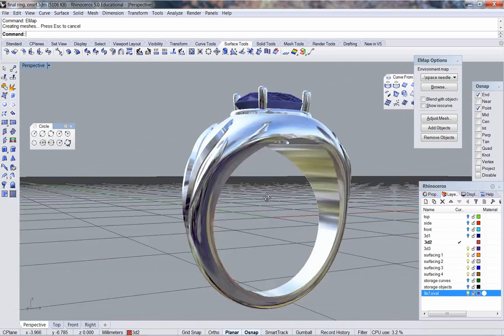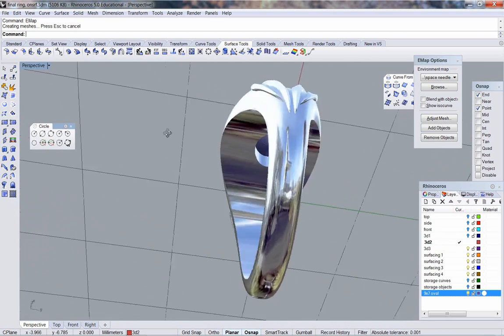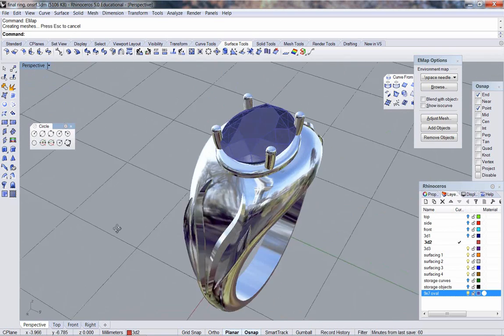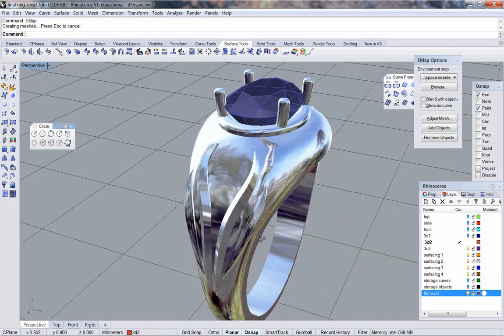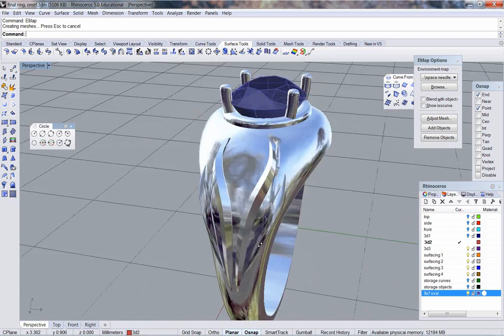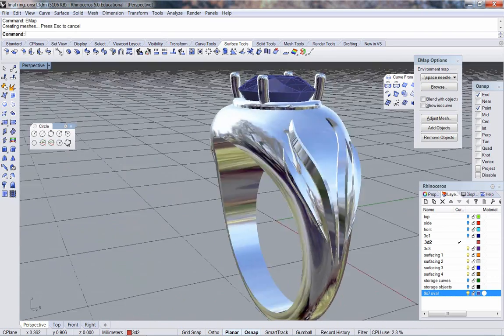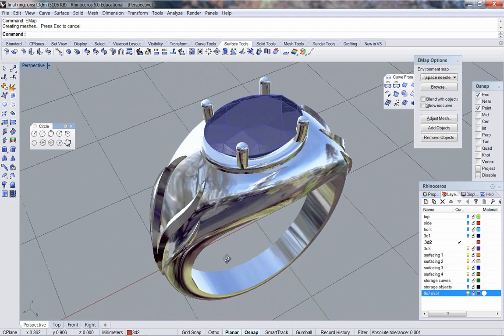Okay, so that's showing applying sculptural detail using swept surfacing and the drawing method of using viewport C-plane set to camera or set to view so that you can draw and project your curves accurately on a surface. Okay? Thanks for watching.